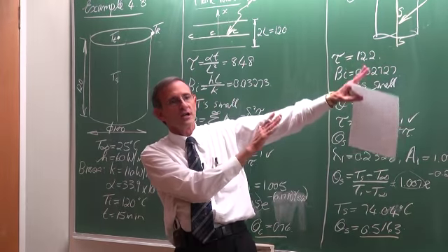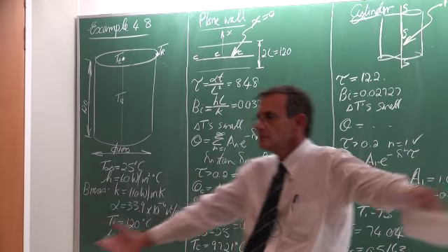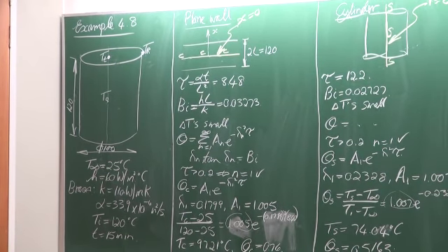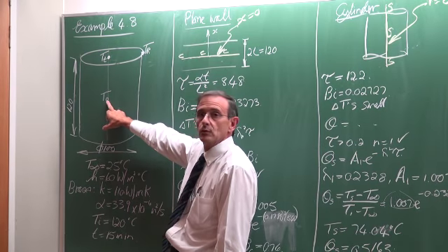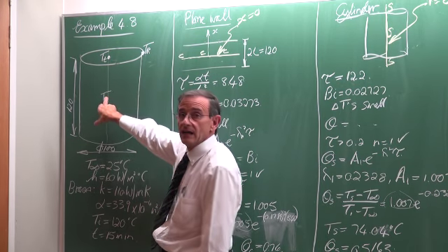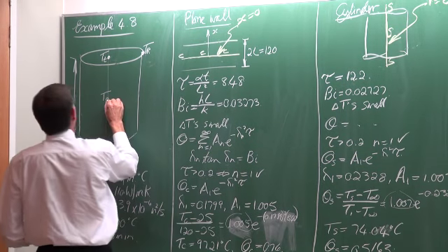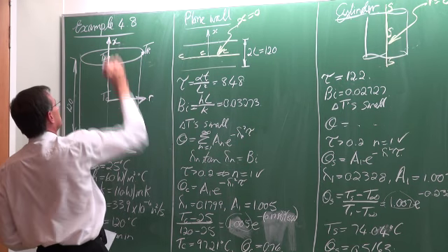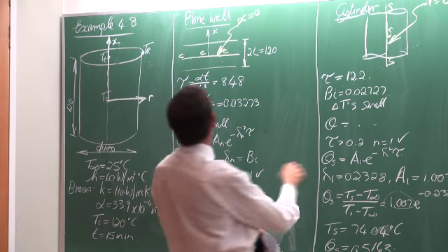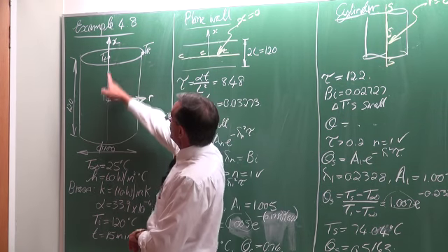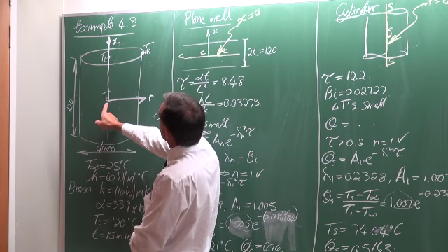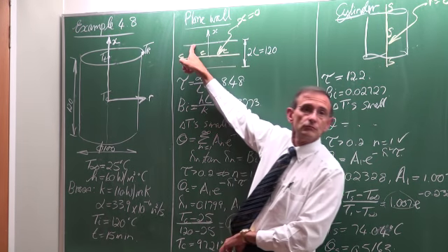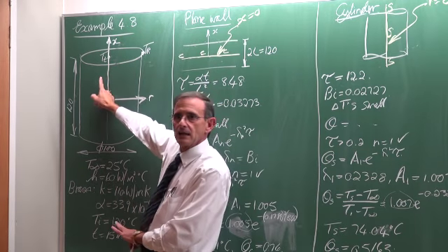Now before I start with the calculations, what would you suggest? If you look at these two solutions of how to get the temperature exactly in the center. If we want to move to that point there, remember our coordinate system is also given in the sketch. So that is R and that is X, and we've been using that all the time. So if we want to move to that point there, that is where X is equal to 60 millimeters. So that is that line there.